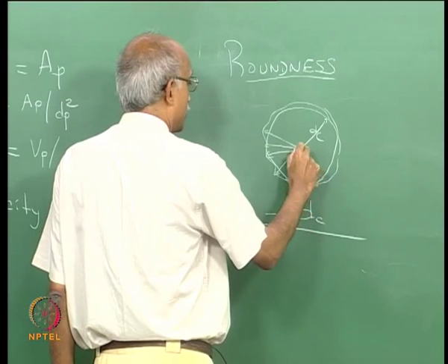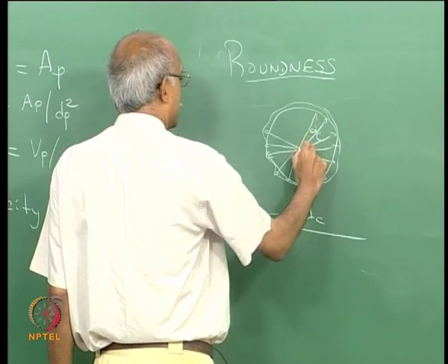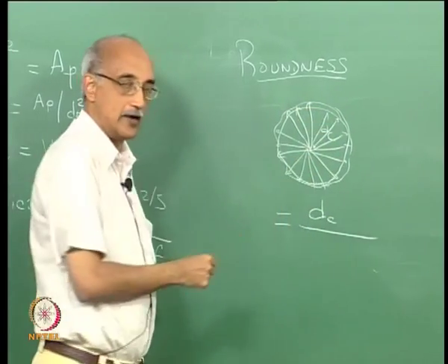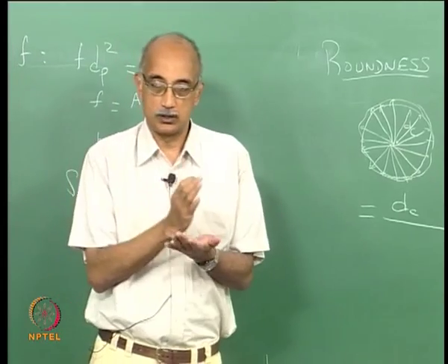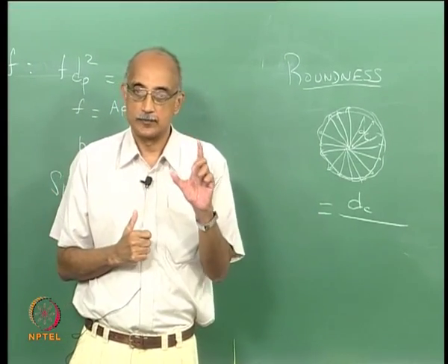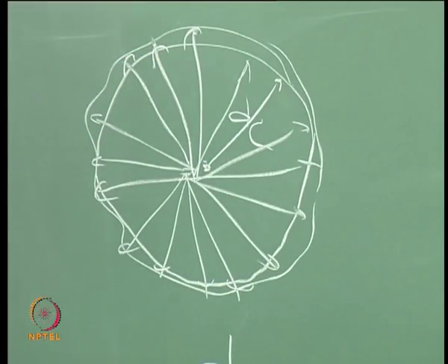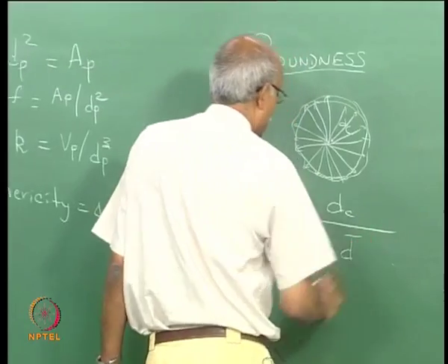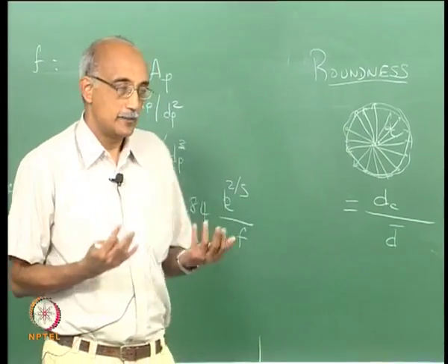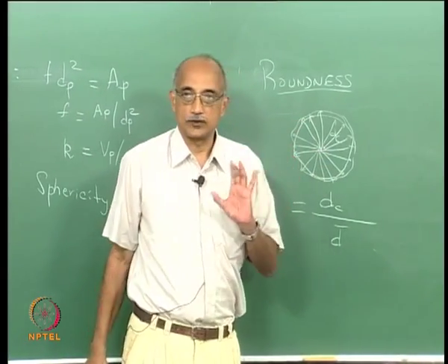So essentially he would draw radii towards all the peripheral points of the object, take the average of the actual radii or diameter that linked the profile of the object to its center, and he would then average it and obtain a mean diameter that represents the actual profile of the object.